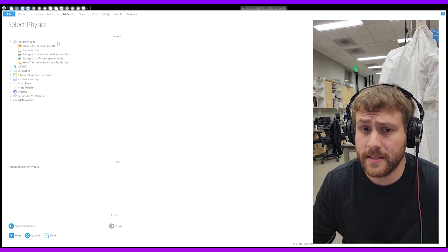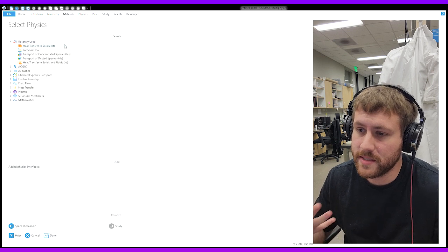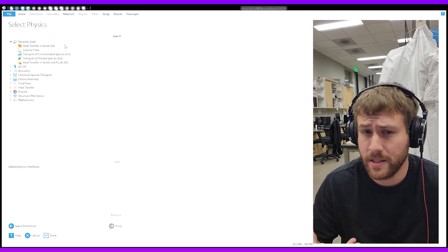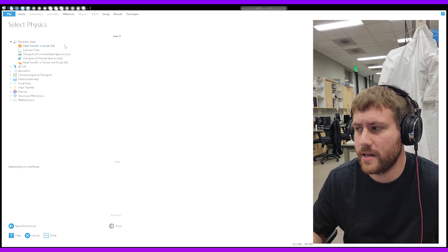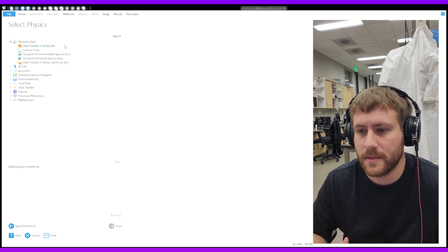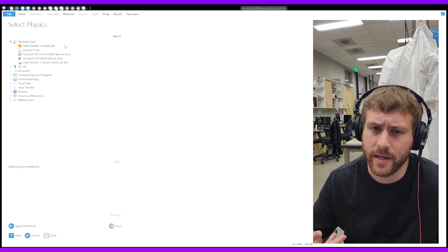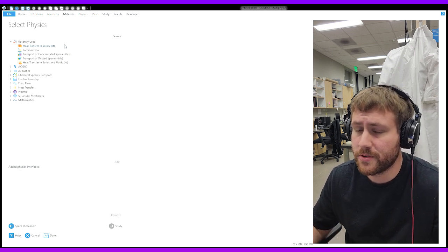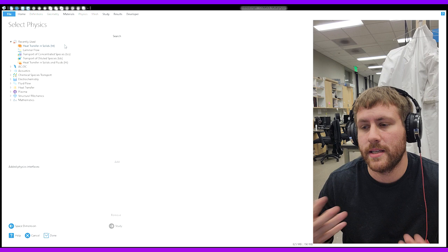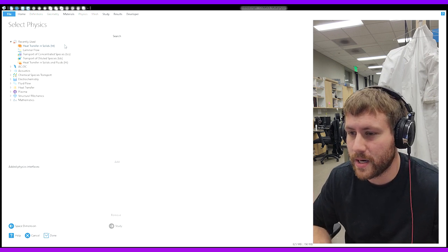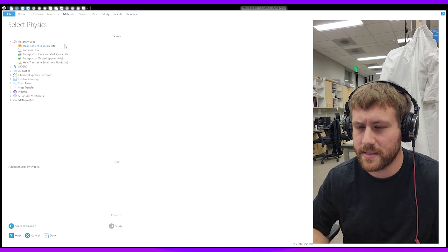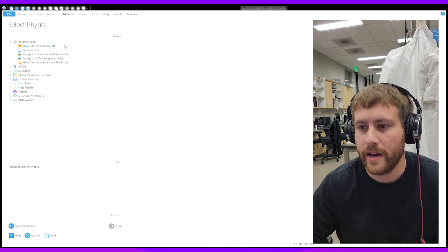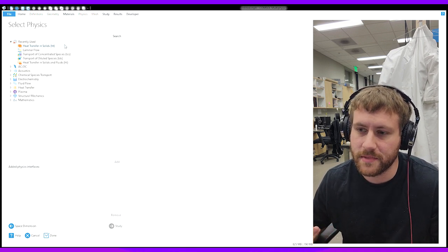The utility of the Model Wizard is, if we pick something like heat transfer in solids, we'll know what parameters are needed to solve the problem. Like, we need thermal conductivity, we need density, we need heat capacities. Just having those boxes there ready to fill in can save a little bit of time. But you can access the physics at any point.